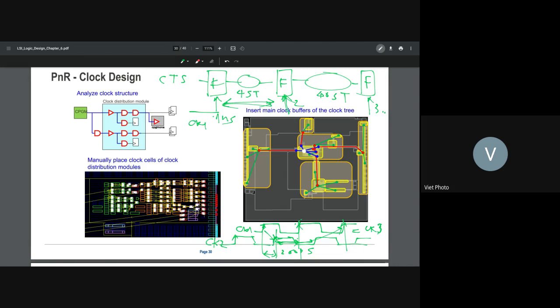That later step actually now becomes included in this one, because during the clock step they route the clock first, and then the timing will be calculated. So after the CTS we will have the real clock, so everything is precise and accurate, and then we can take it and estimate the timing, and it will be accurate.